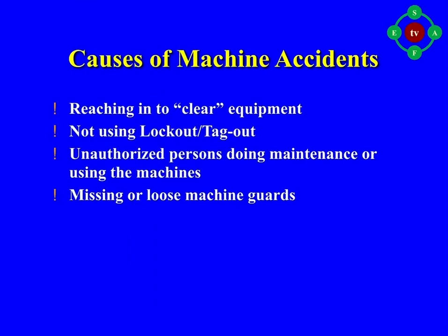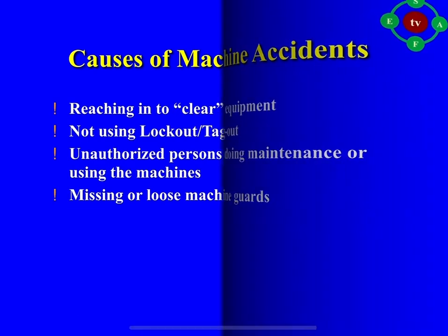Causes of machine accidents: reaching in to clear equipment, not using lockout or tagout, unauthorized persons doing maintenance or using the machines, missing or loose machine guards.